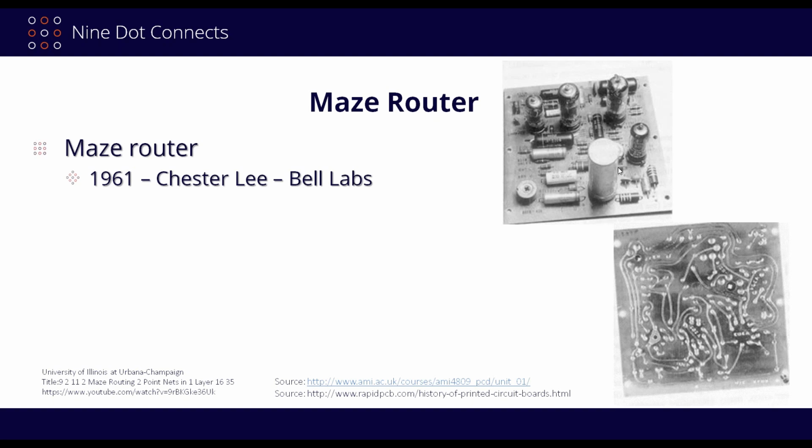And if you take a look at what these boards looked like back in the early 1960s, there would have been a definite need for this because, again, what they were doing there is you only routed on one side. So the top, what they called, and we still to this day call it the component side, is where you place all your through-hole components, and on the bottom side is where you would solder it.